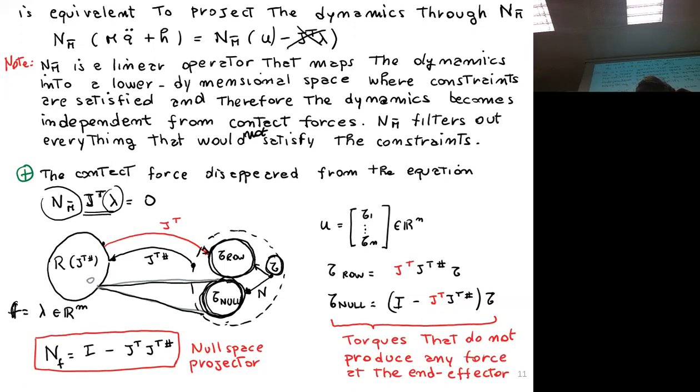So this is also useful, for example, if you want to do inverse dynamics. This time we don't have anymore the acceleration dependent on both forces and torques, but only on torques. So we can compute a one-to-one relationship between the acceleration and the torques.